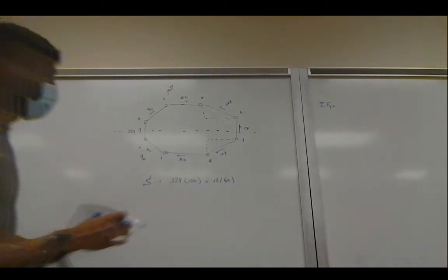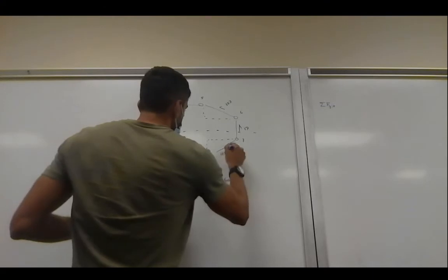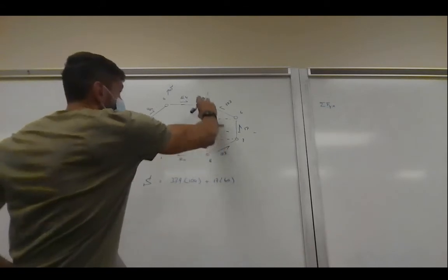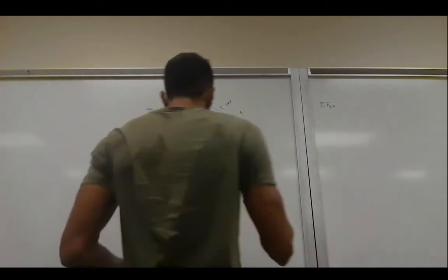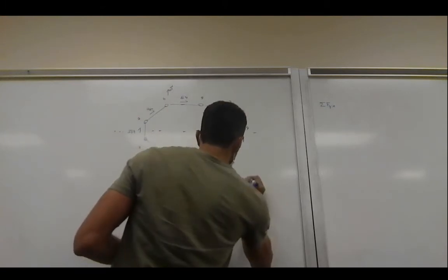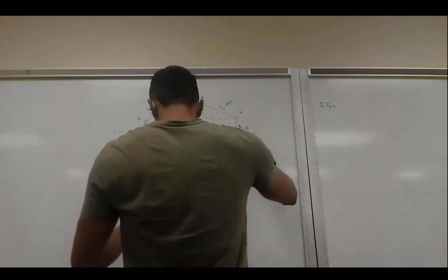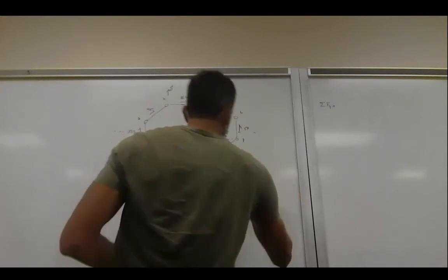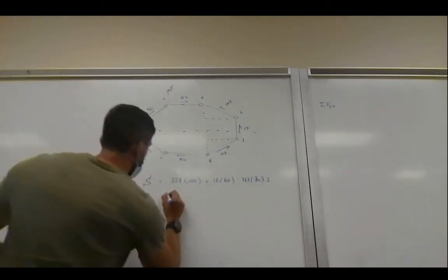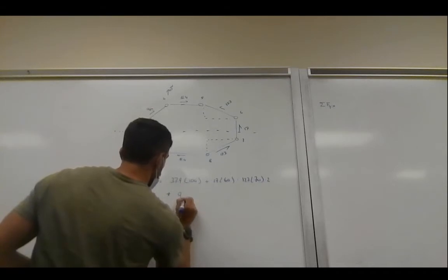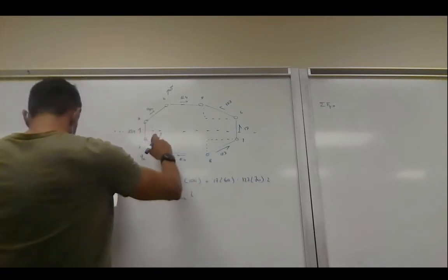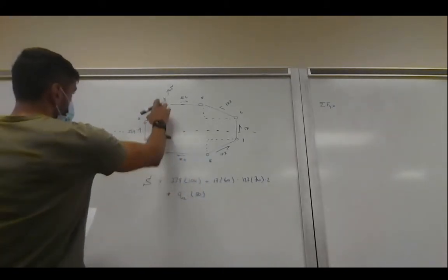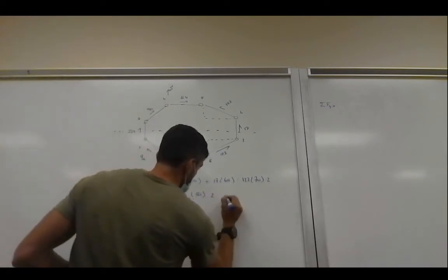Okay, I thought I did something wrong. This one is this way. That one is that way. Okay, good. Both of them have the same vertical component. Both of them are positive, okay? So that means 12.7 multiplied by only the vertical component between points 8 and 7, that's 70. And because you have the same here, we can multiply by 2, plus the vertical component of Q12, which is the difference in y direction of 1,2, and that's 50. And because this is pointing upward, that can be multiplied by 2 as well.